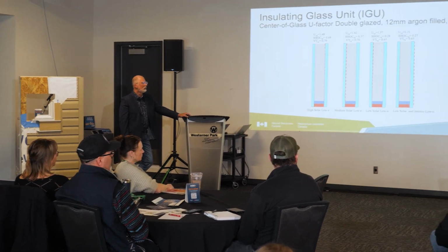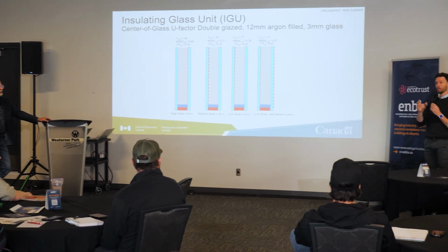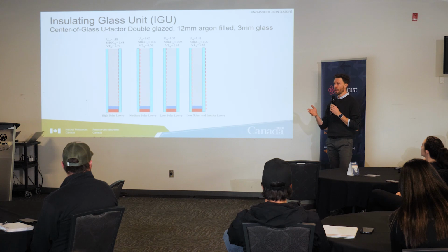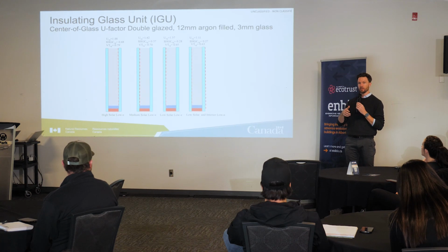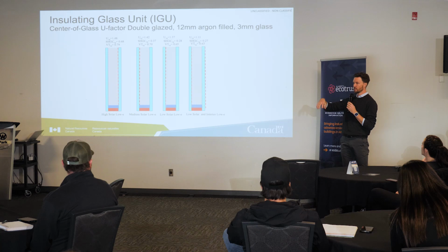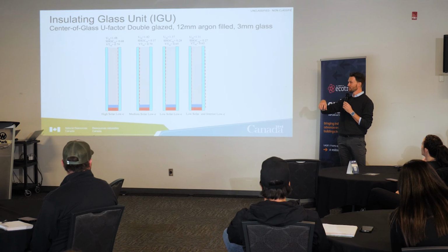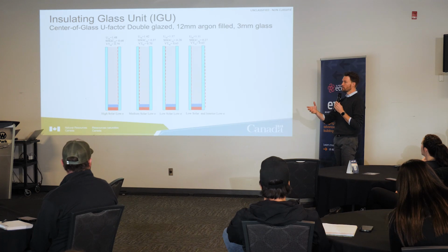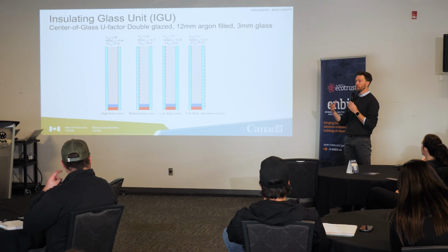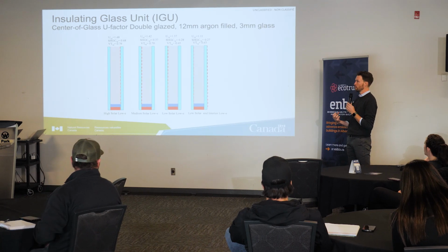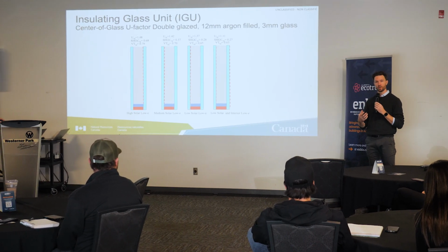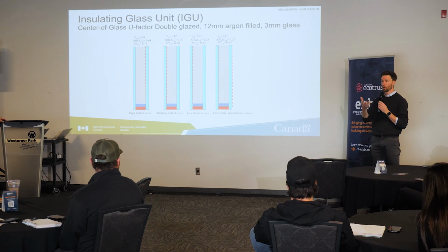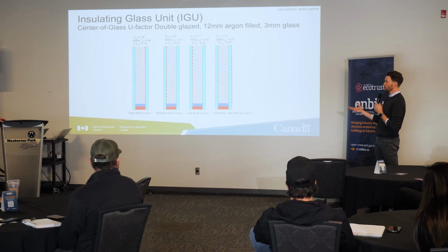I would suggest that customization by orientation is a different problem for those two different categories of home builders. Wouldn't you agree? Like if you're trying to track different windows on different sides on a model that is being built in different orientations in a subdivision, that's pretty complex. Feels to me like the chances of maybe putting the wrong window on the wrong side are pretty high. In a custom home scenario, you've got a lot more ability to control that. You're getting one set of windows and you have that chance for optimization. So I think maybe keep that in mind as we think about consistency and simplicity for your process versus the ability to fine tune windows with this.